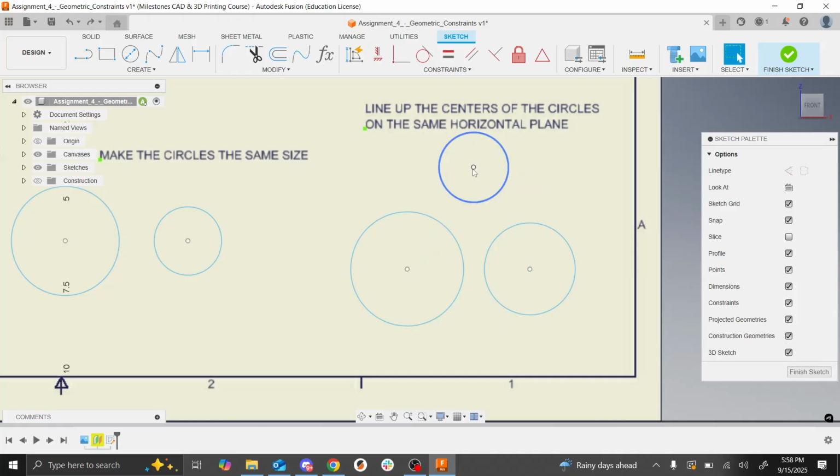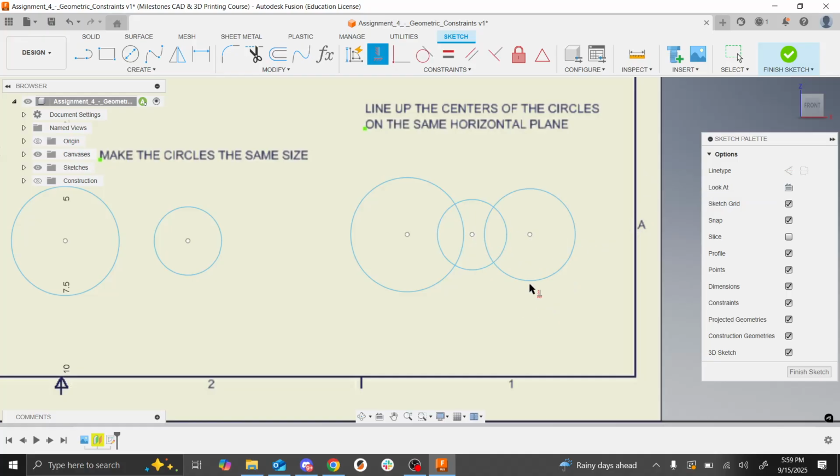So you might have to suggest it a little bit. So I'm moving this, and you can see now it's closer to horizontal than vertical. So if I apply it, then it becomes horizontal. Same thing with this. Now it's horizontal. Does that make sense? That's a little annoying thing about CAD because sometimes it just doesn't do what you want it to do. So you have to make it easy for the computer to know.